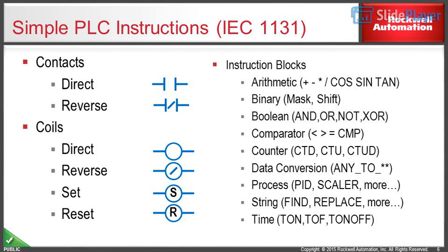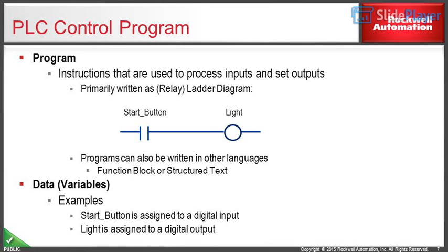PLC control program: instructions that are used to process inputs and set outputs. Primarily written as relay ladder diagram. Programs can also be written in other languages, such as function block or structured text. Data, variables. Examples.